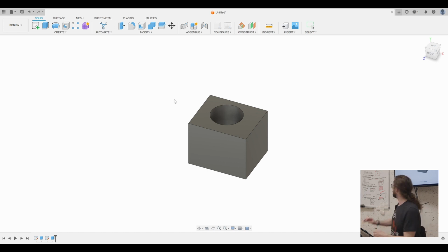So you're going to have to re-save it. You're not going to be able to slice an F3D. You can slice a 3MF. So if you want to save it for later, you would have to reopen it and then save that again as a 3MF, which is fine. That's not a big deal. But with what we're doing, an F3D is a dead end of just the modeling part.